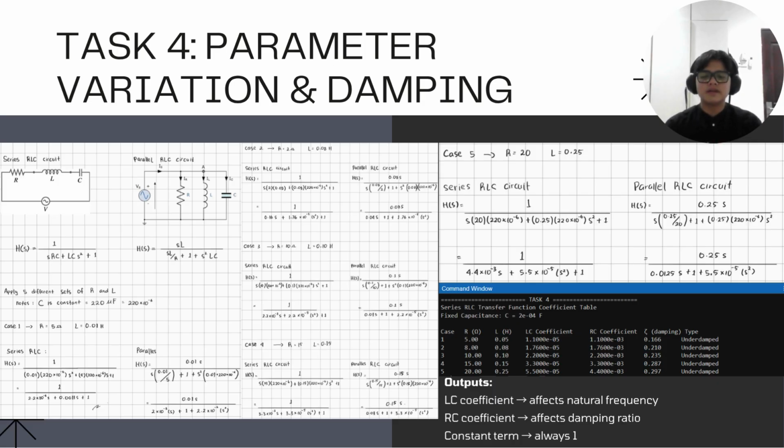In task 4, we varied R and L values to observe their effect on damping. We calculated the LC and RC coefficients from the transfer function. LC influenced the natural frequency, while the RC controlled the damping. Lower R and L values gave a faster but oscillatory response. Higher values resulted in more damping and smoother but slower voltage transitions.